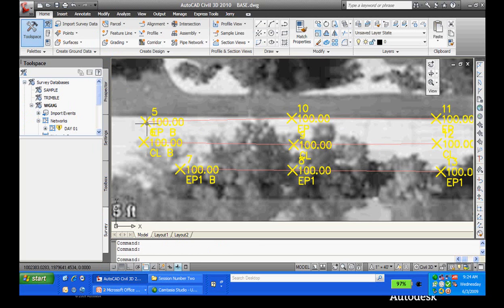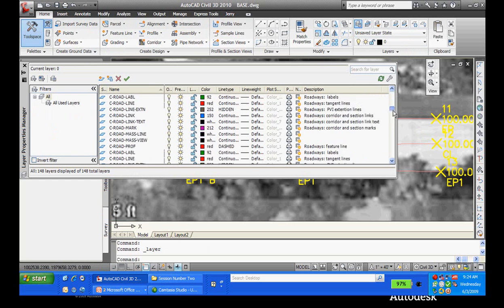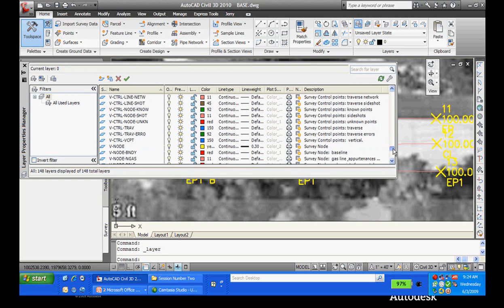It processes it, and you can see that I didn't click very well with my shots, but we can see the line work. Those lines don't show up that great, so let me make a quick change here. I'm going to change my layer. Actually, we'll do it through this guy. What's displaying that on the screen is a style. It's a curb style.